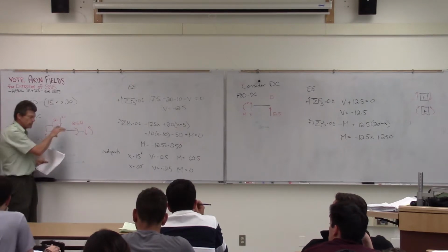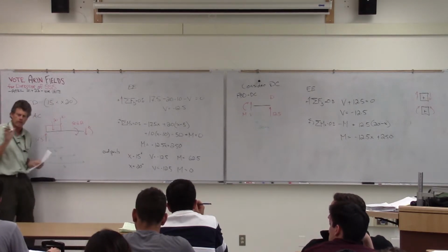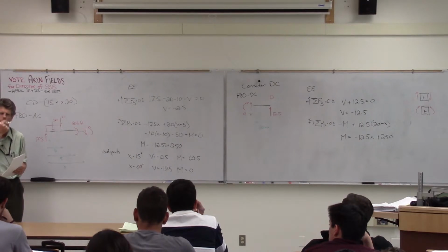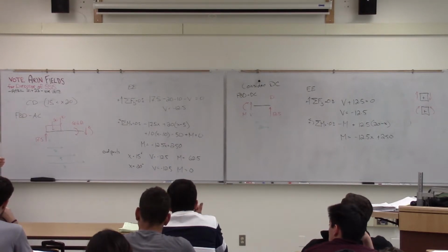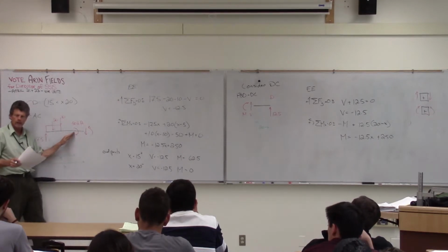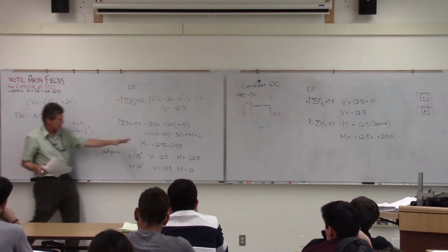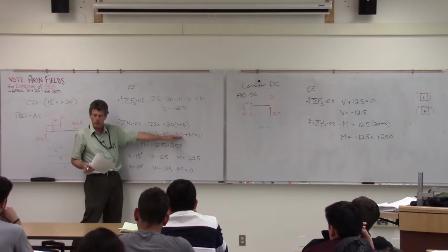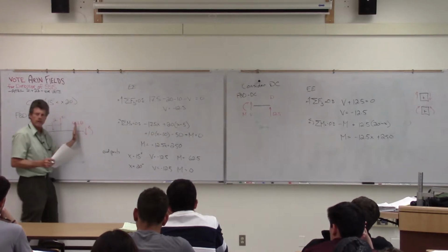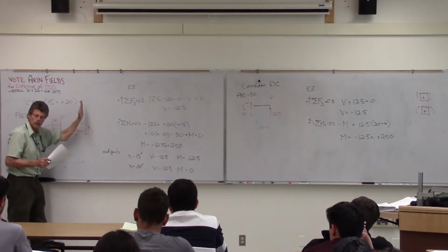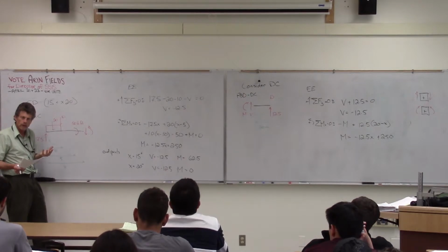So it doesn't depend upon any distance. Remember, that's that free couple. Remember way back when we were talking about free couples and free vectors and that sort of thing? That's what we call that. That's that free vector. What that means is then I just freely plug it into the equation. Because it doesn't matter whether I'm here or here or here. Basically, it's going to be the same twist to the body.